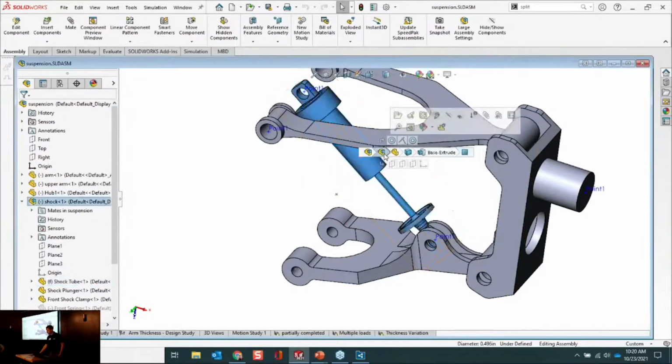So let's say I want to select the subassembly in the screen. Now I can also get the origin and the planes for that. What is that good for? Mating. It means you can just literally click on something. You don't have to go over here and filter through the tree any longer to find things so that you can mate to it. You can just select the thing in question and hit the D key.